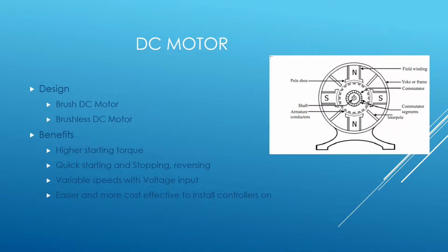A brushed DC motor uses a configuration of wound coils as the armature, acting as a two-pole electromagnet. The current's directionality is reversed twice per cycle by the commutator, a mechanical rotary switch. This facilitates a flow of the current through the armature. Thus, the electromagnet poles pull and push against the permanent magnets along the outside of the motor. The commutator then reverses the polarity of the armature's electromagnet as its poles cross the permanent magnet poles.